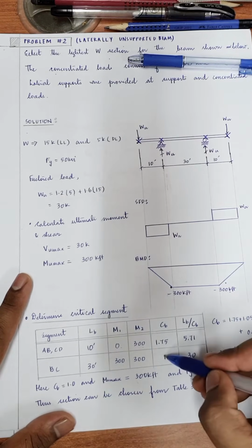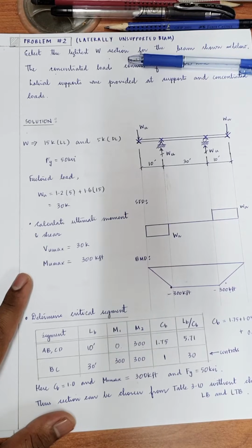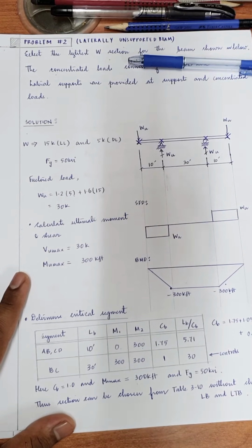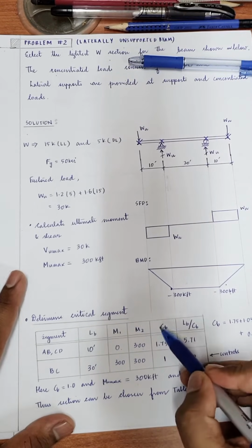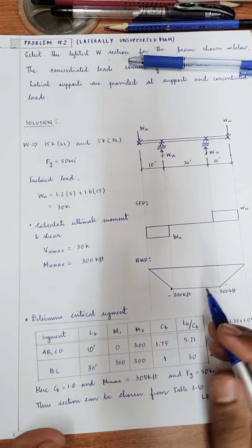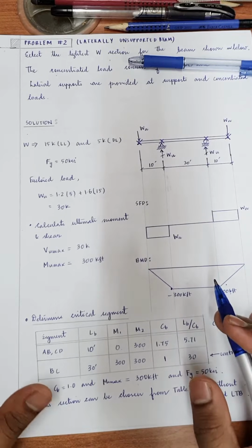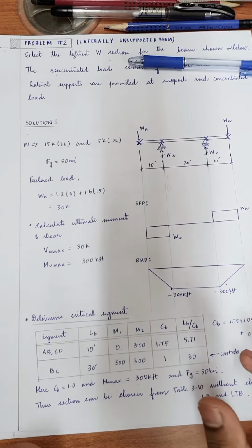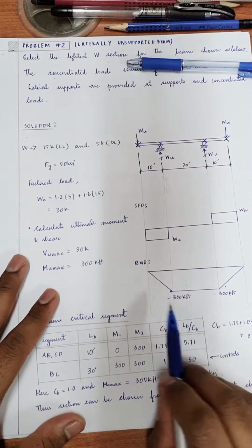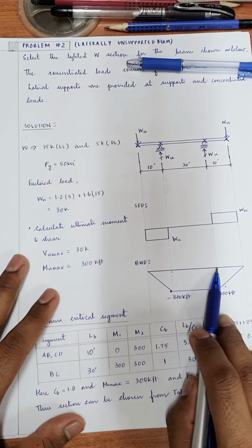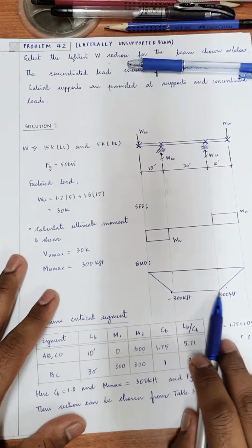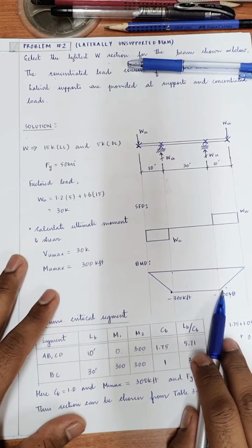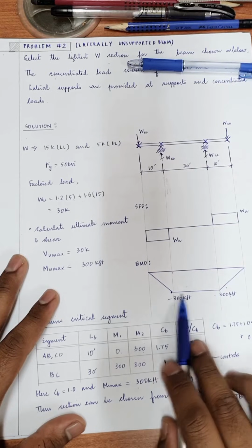Now the idea of CB is to be discussed here. You had already learned in the lecture that CB is like a ratio representing how much of your beam segment is actually utilized. For example, if you consider this segment between these supports, the entire segment is loaded with the same moment, which means that your entire beam is taking the maximum bending moment.